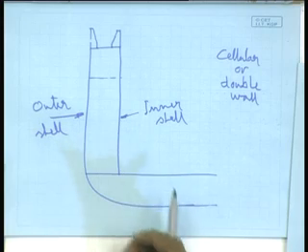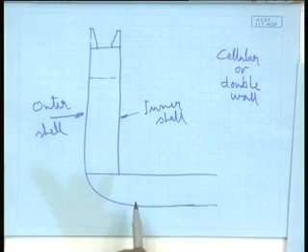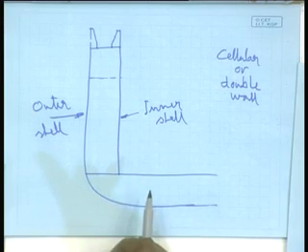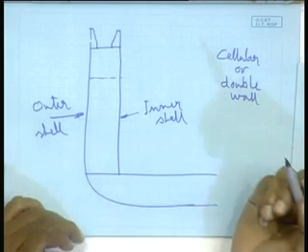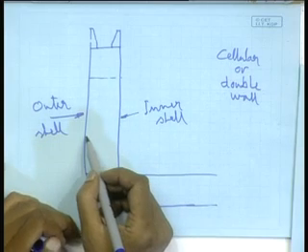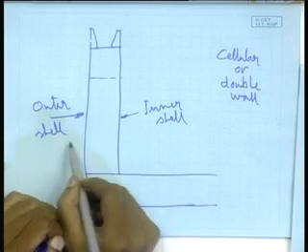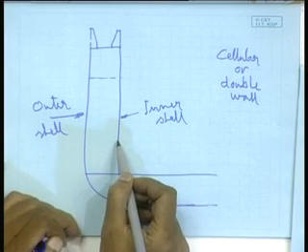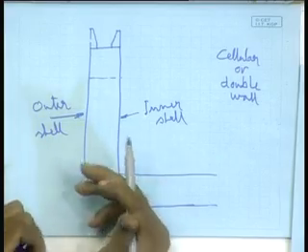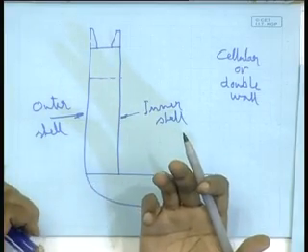So, in the process, what have I come for? We have come for a concept of cellular construction or a double wall construction. That means, instead of one side shell, I have two side shells. But this will increase the weight. This will not only increase weight, it will increase cost, everything it will increase, but it is needed to provide for the required strength.